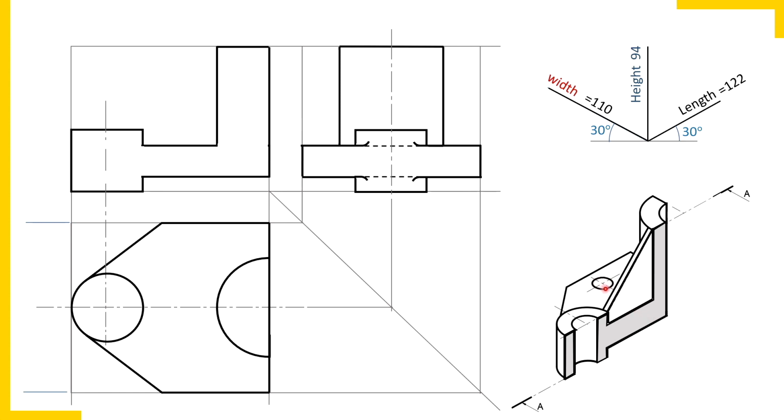But what about these 2 holes? There is a hole on the back side in the horizontal plate. Similarly, there was a hole on the front side. These 2 holes are not getting cut. So the rule in sections of solids: remember, some hidden details get exposed because of cutting. Those hidden details will be visible in sectional views. Some hidden details remain hidden even after cutting. Those hidden details we need not draw in the sectional view. Remember, no hidden lines in sectional views. Let's proceed.